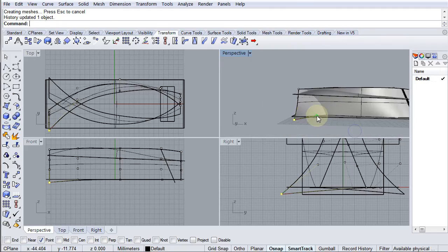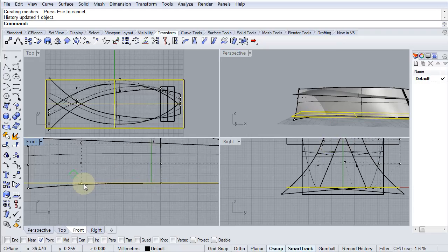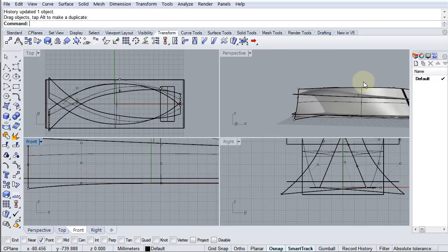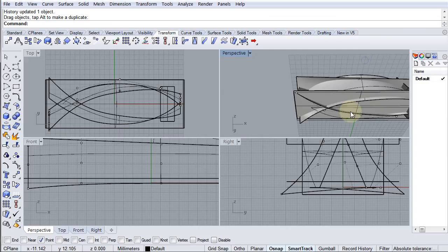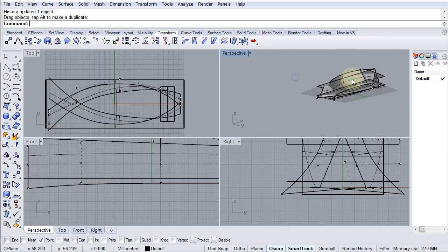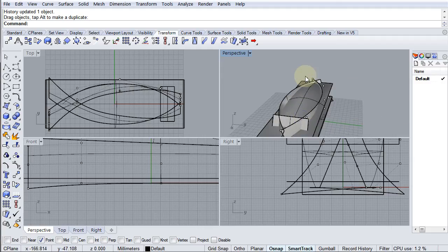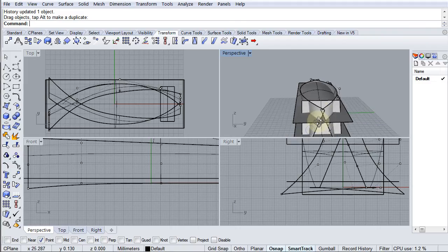Okay. The last thing I'm going to do is take the base surface here and just move it up a fraction. And the reason for that is to ensure that I have full intersection in the bottom here. So I have intersecting surfaces all the way around my object. They will contain a volume now inside. There would be a volume inside there, and if all those are sealed, there's also no double volumes. I haven't trapped 2 volumes. I haven't got any figure of 8s where 2 volumes could confuse the tool.